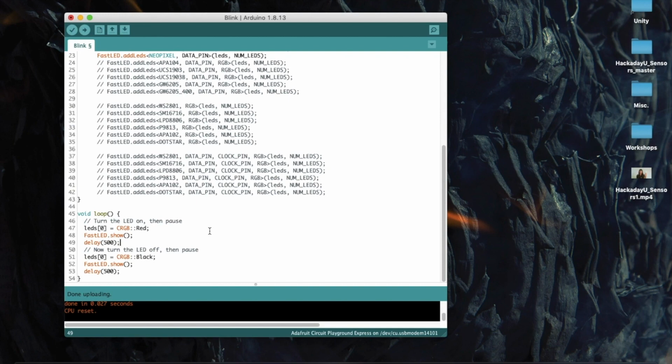At its ordinary speed, the Arduino operates much too fast for humans to perceive, so we need a way to change our lights more slowly. Note that delay is not the way you should do this in non-demo code. We'll explain a better way in the next class. The only confusing thing here is FastLED.show.